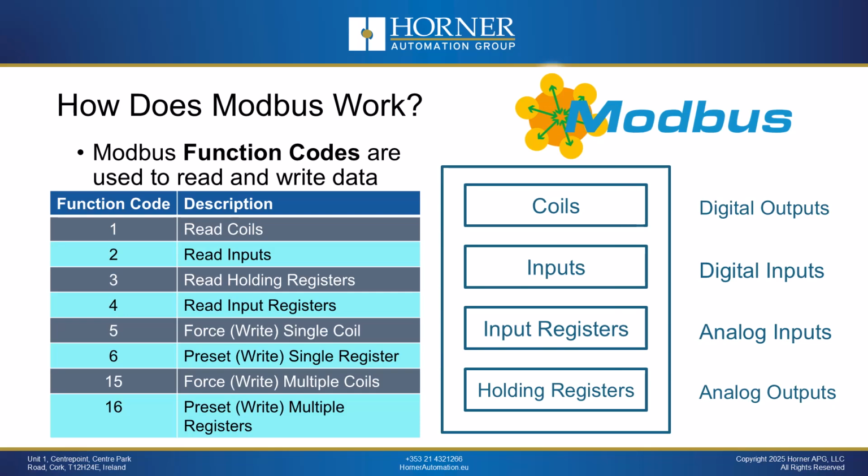Next, we will look at Modbus function codes. These are the commands usually in the background that will act as the Modbus master. The OCS is executing these function codes to communicate with the drive. However, you don't always need to know specifically which function code is being used. You just need to understand what function codes are there and which ones are supported by your particular drive.